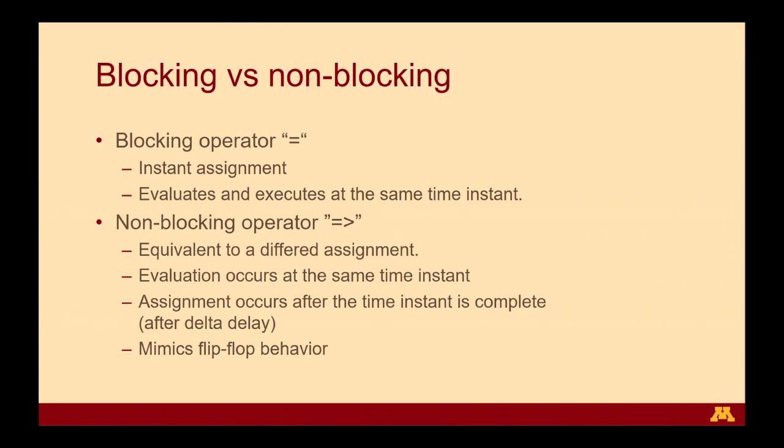And I find it non-intuitive. I would think the first one would be called non-blocking, and the second one would be called blocking. I find the naming non-intuitive, whoever named this. So the naming convention is based on how it behaves in the code. If you have a sequence of code and you write it with the blocking operator, it will not proceed to the next step unless this line completes. Okay, I see. Yeah, that makes sense. Okay, go ahead.